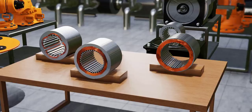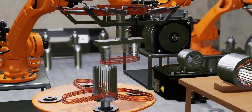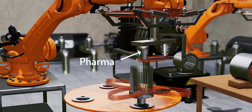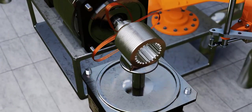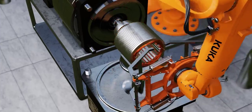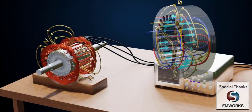Here you can see the more complex windings wound on the stator. These winding types are selected according to the applications you want to use the motor in. In the factories, these coils are wound on a former. At a time, 2 to 3 sets are wound on each side. This former loaded with coil groups is inserted into the stator core by hydraulic pressure. Then comes the human intervention to make precise connections between these coils. Then the windings are tested and sent to operate your mixer grinder, washing machine, or your air compressor.